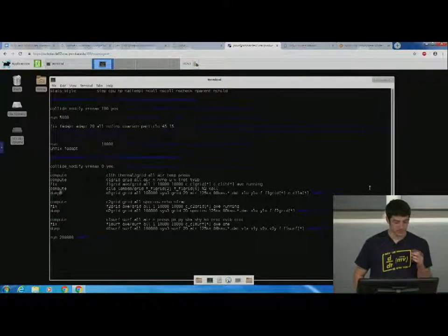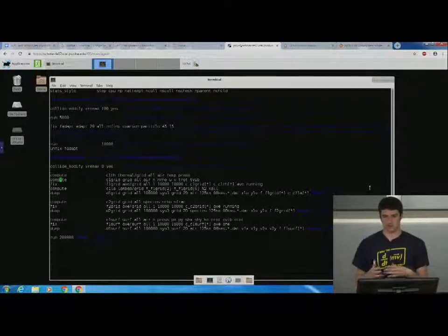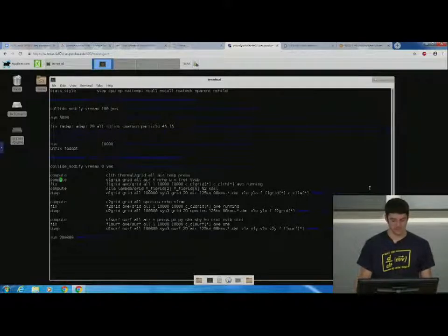So I'll have to go through this quickly, and this is something really good to reference the manual for, since there's a bunch of small syntax things which I always mess up many times before I finally get it. So you really have to go through the manual to make sure you're doing it right. But this one's compute, so every time step I'm going to be computing some properties here. Then I call my compute ID c1 grid. Then I say I'm computing grid, so this is the flow field property. All means I believe I'm going over all cells. Air, so I'm computing for the mixture air.